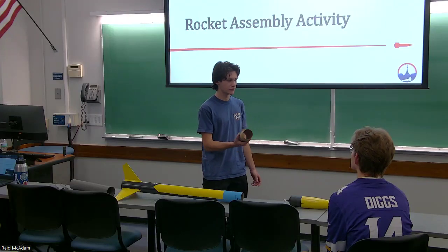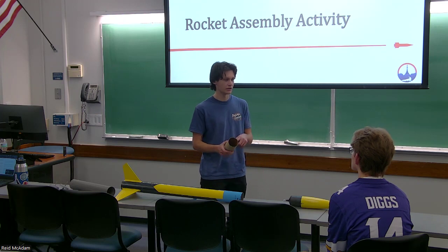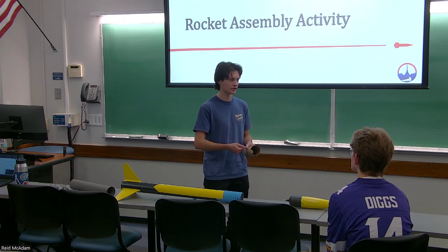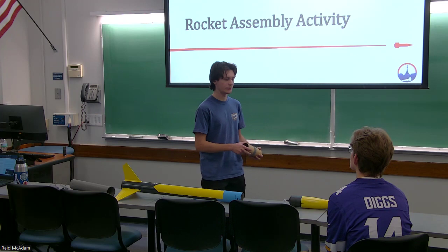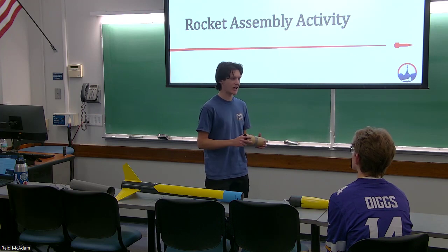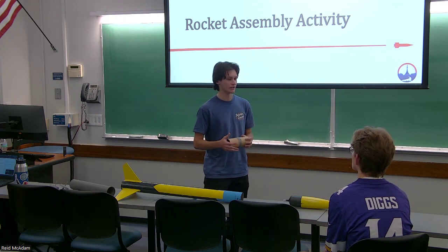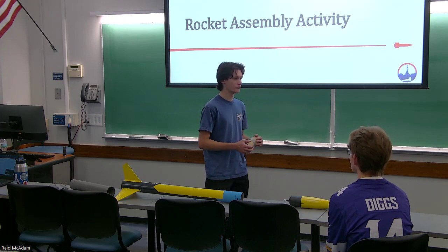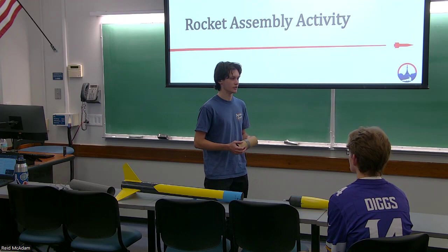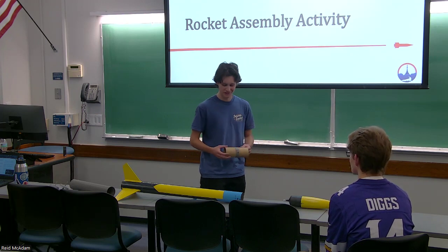The main thing for this switch band is to hold my push-lock switch, which arms the altimeter. Until the rocket gets onto the pad, you want to keep the altimeter not activated. That way, you don't accidentally set the ejection charges off near people.